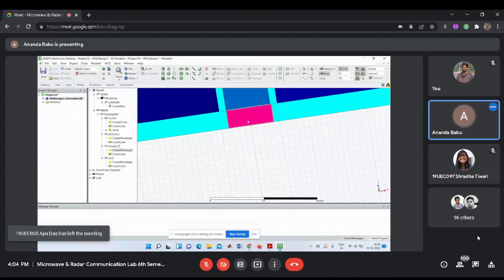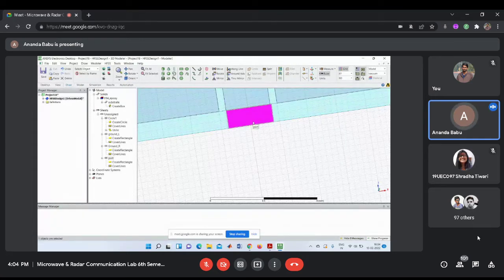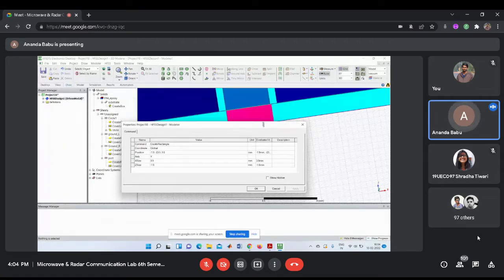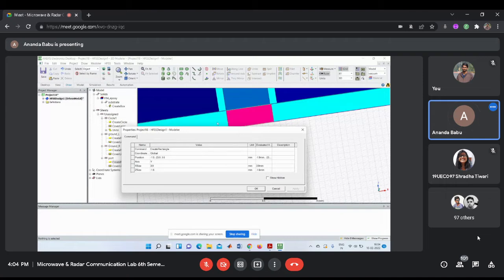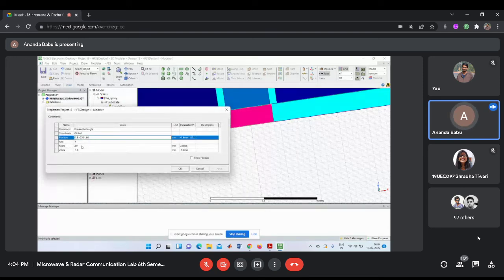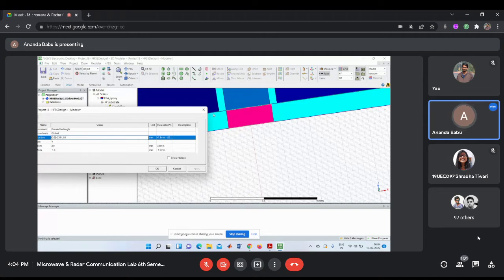So that's why I am increasing the dimensions of this pink color rectangle. Simply click on this. We are giving the port here. See the port, it was blinking. Generally, whatever the dimensions are, we take minus 1.52. We are varying the x value, so don't change y and z. Increasing the x value, simply observing, this is minus 1.9. So I am giving 3.5, so here it starts at minus 3.5. Minus 3.5 means the left side increases. So 3.5 doubled is 7.